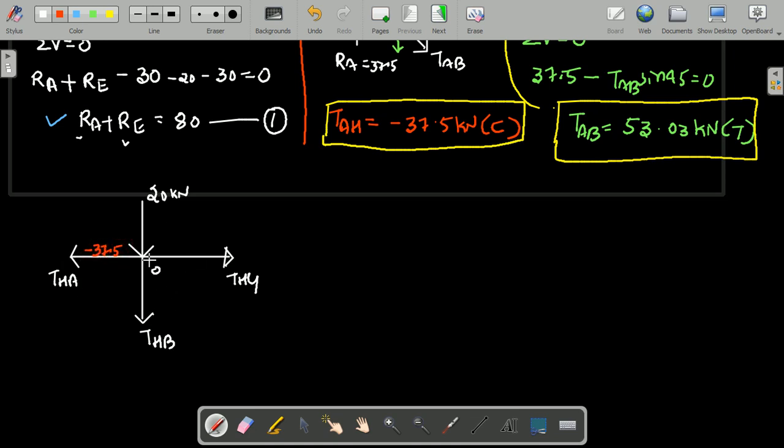So 4 forces, this is in the form of a coplanar concurrent force system. Which joint is it? It is joint H that I have considered now. Coplanar concurrent force system is there, 2 unknowns are there, so we can find them. We just need to apply the equilibrium condition, summation of horizontal force is equal to 0. In this joint we do not have any inclined forces.